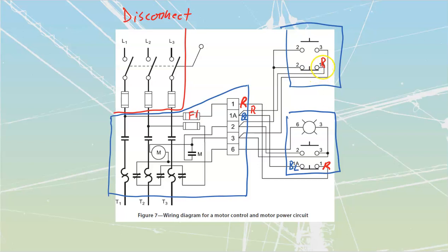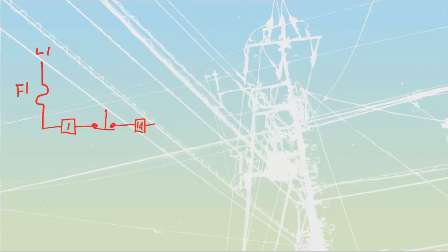So I'm going to draw in, well, sorry, not a switch, it's a normally closed push button. I'm going to have a normally closed push button that goes across to another side. We will draw that in. Now I've got 2 normally closed push buttons inside of here.